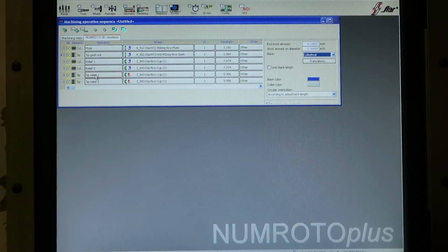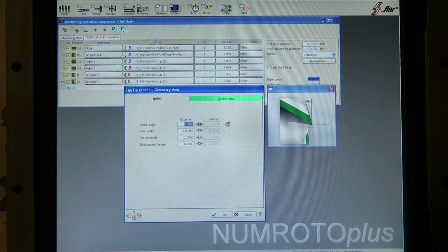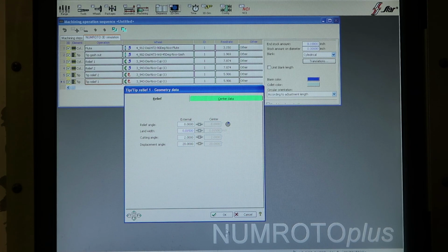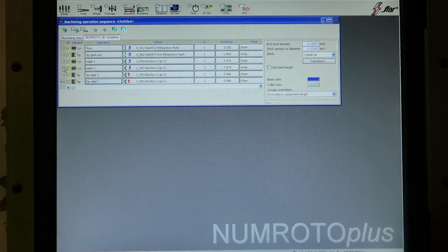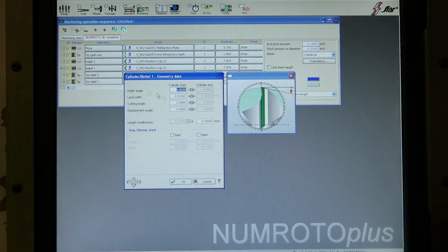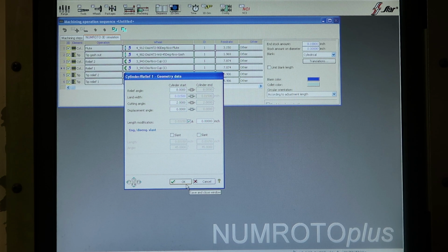What else did I say? Oh, I'm going to move the primary clearance last on the grinding, and we're going to decrease the width of this land to 15 thousandths. And also I'm going to reverse these, so I do the OD's primary or cutting edge clearance last, and I'm going to do that at 0.015 as well on the width of that.